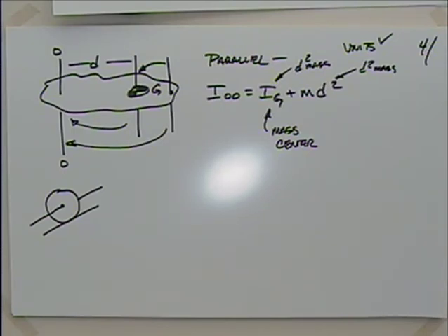Okay. And as we'll see tomorrow, as we go through the cycles in the 4-stroke engine, that flywheel not only continues to cut the grass during that time period, it actually drives the engine during that time period. The compression stroke is made possible by the flywheel, right? So if we start to lighten up the flywheel, it will begin to run quite rough. Now, if you've ever taken apart a lawnmower, you might find out there's no flywheel in this thing. So did I not learn this right in the dynamics class, or what's going on here?